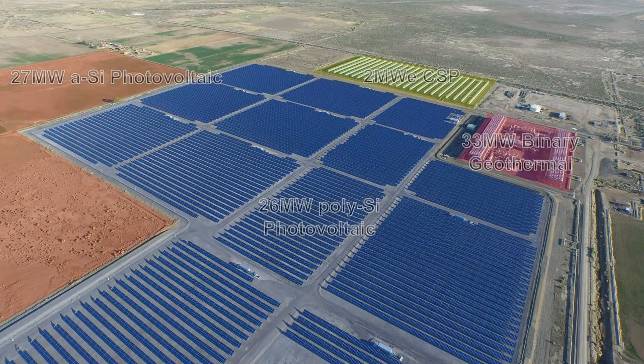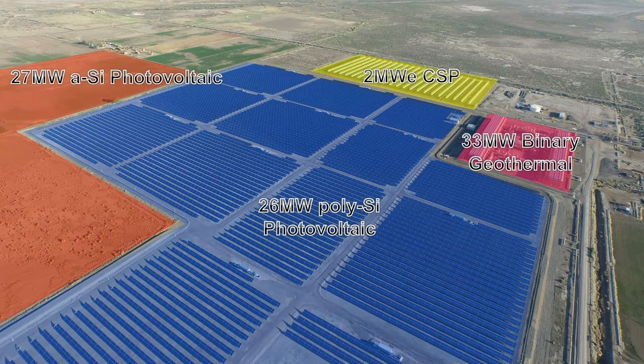So this is one of our flagship facilities. It's located in Nevada, and this is why I have a lot of experience with inverters. So this is what we're actually looking at here. The heart of the plant is a 33 megawatt binary cycle geothermal facility. We use inverters from 480 volt all the way up to 5 kV native for running electric submersible pumps and fans and various auxiliary equipment.